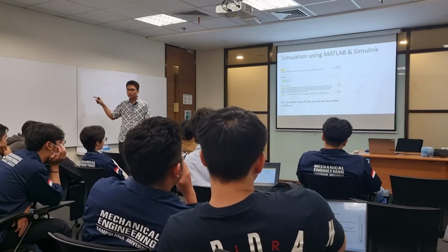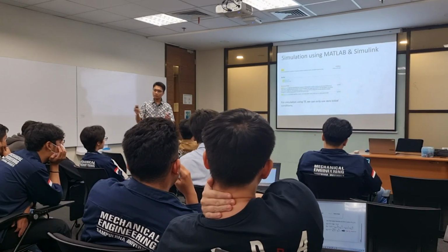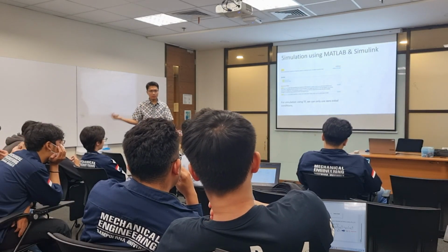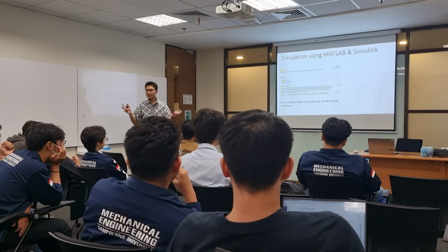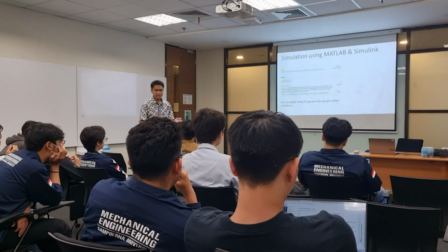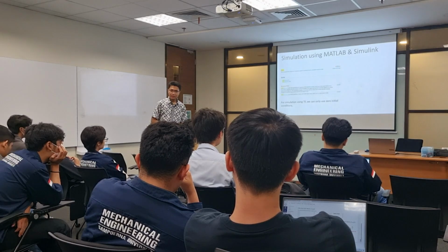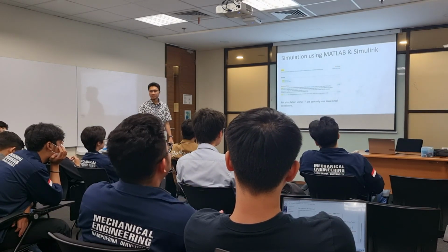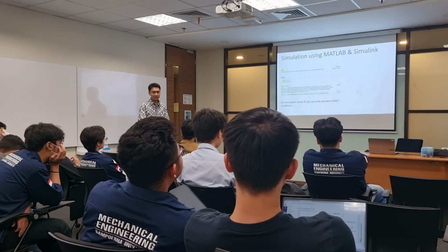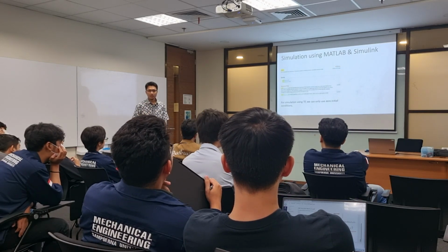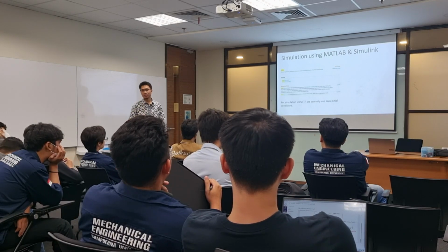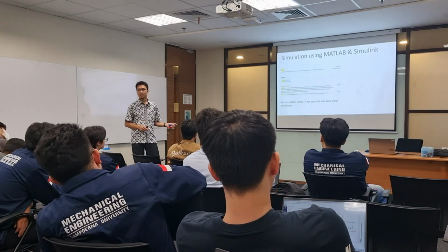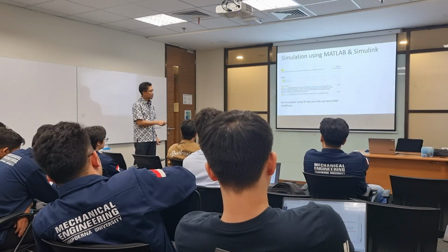After we get our transfer function in MATLAB, we want to simulate it. We will not just leave it there and go home. No, no. We create the transfer function model in MATLAB so that we can do simulation, right? So how do we simulate it? The easiest way is using LSIM. LSIM stands for linear simulator. The L comes from linear, because the transfer function that we have is a linear system.